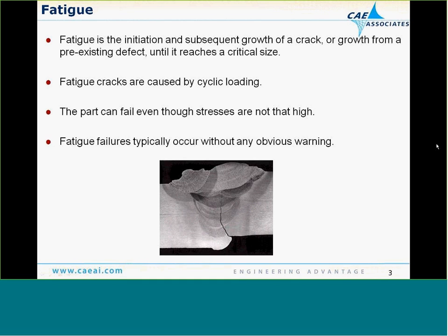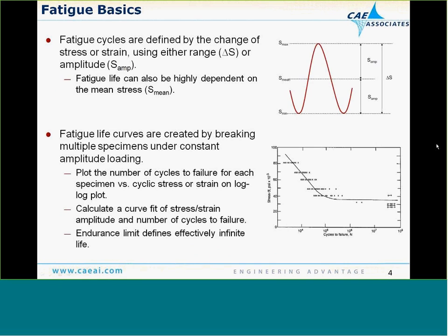Fatigue is the initiation and growth of cracks. Usually they start from a defect in the structural part, and based on the application of cyclic loading, these cracks will grow to failure. The issue with fatigue is that typically the loads are much lower than would cause failure from a static sense. So you can have very small loads applied in a cyclic sense. These will grow cracks to failure, and typically you'll get very little warning when a fatigue failure will occur. So thus, prediction of life using fatigue is very important for any engineering product.